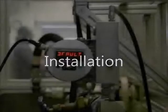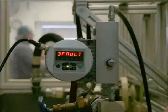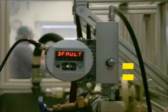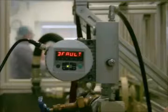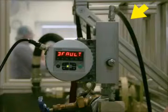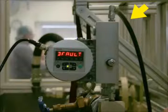This slide shows the basic installation of the TCM. As you notice, the flow is south to north, and we do that so it creates a back pressure to the unit. One other thing is that we want this hosed in rather than hard plumbed. This hose should be no smaller than 4 millimeters.